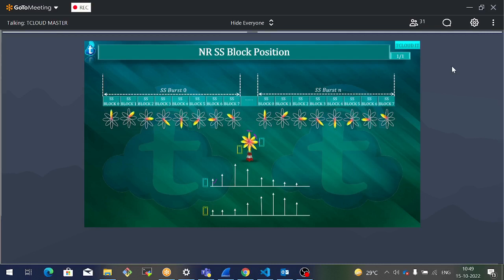But when you read SS block 2, this aqua color mobile picked up the highest signal strength among the other SSBs. As you keep going around this circle, because these beams are all the other way around completely, mobile would definitely be getting less signal strength on them. So signal strength keeps reducing. So mobile would detect that, okay, this beam is operable for me. This is giving me the highest signal strength.